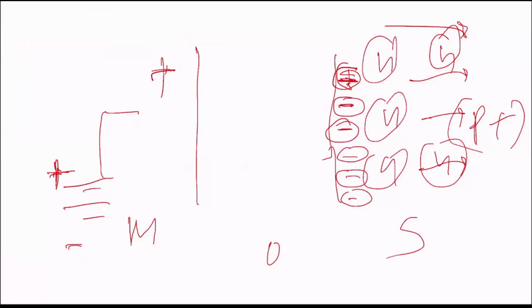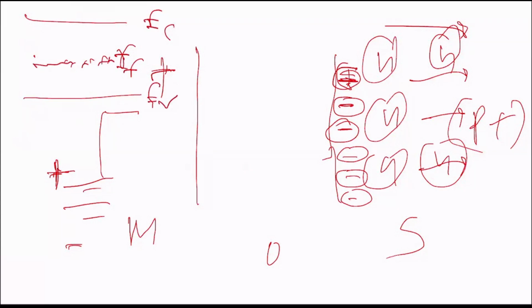If you have an intrinsic material, the Fermi level is just at the middle of the conduction and valence band. But if you have a p-type material, the Fermi level moves towards the valence band. Right beneath the oxide layer, we have more negative charge. This is no longer that much of a p-type material.